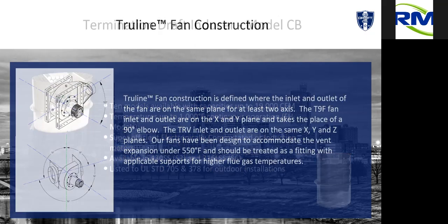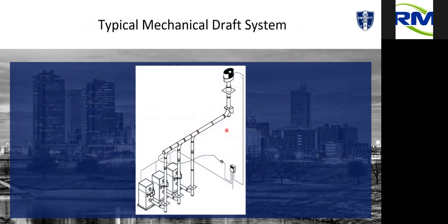Question came up, and I'll back up a slide since it popped in, asking about a drip leg on the boiler's stack, asking if it's good practice. So this is something that is dependent on the system, and it depends on the appliance as well as the vent manufacturer you're working with. All we ask for is that if you're doing an inline fan, which we'll show you in a minute, that we are not your system drains. So your condensate drains are very manufacturer dependent. So you work with, again, your staff member or your sales member, and they can help you out designing that. So hopefully that answers the question.